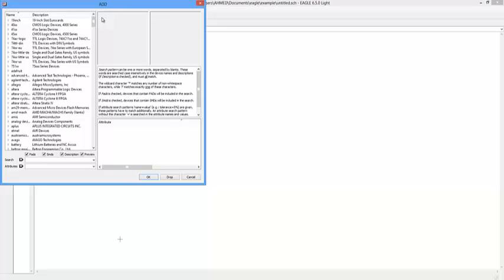Mostly the H-bridges that people use for this are two types, either L298 or L293. L298 for this purpose is overkill because that one is like 2 ampere drive current. L293 is more than enough. I think it's 0.5 ampere per channel, so it should be enough to drive any small DC toy motors, not big beefy DC motors.